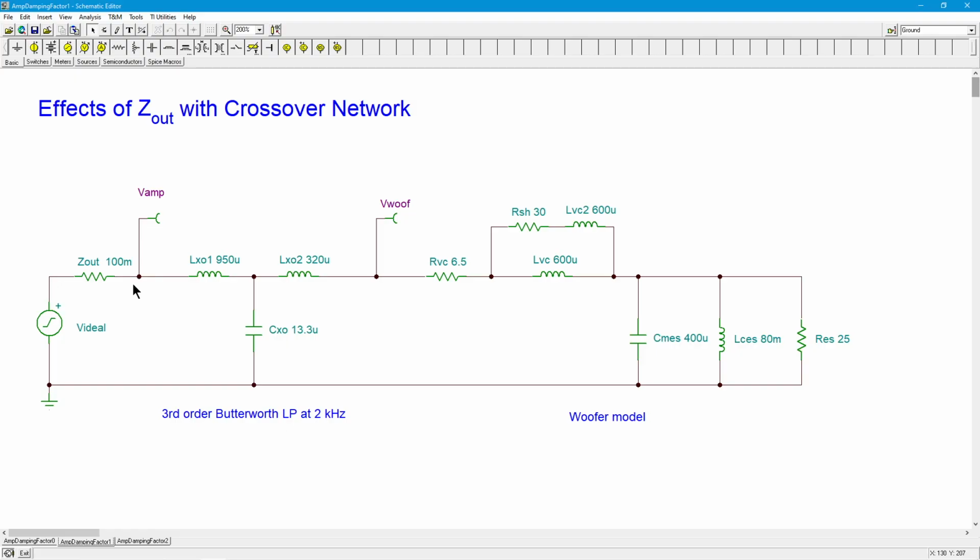So a low impedance, in other words, a high damping factor, is going to get rid of or mitigate resonance effects on your loudspeaker system. And that's a sonic improvement. The question is, how far down do you have to go? Well, visually what we're looking at here is vanishingly small deviations once we got down to this 1/10 of an ohm. That's going to give us a nominal damping factor of 80. 8 ohms is the nominal impedance of our loudspeaker model, 8 ohms over 0.1, so there's a damping factor of 80.